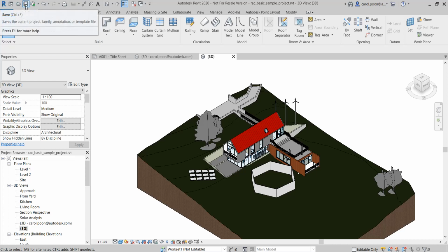For the save button, actually, if you have no connection or something happened on BIM 360, you can click on the save, because once you have clicked the save button, your Revit model will be saved in your local computer. And then after your internet connection comes back, you can click on this synchronize again. Synchronize includes several actions in this icon, which means save a copy to your local computer, synchronize your model to BIM 360, which includes upload and download the models. So we usually use synchronize.